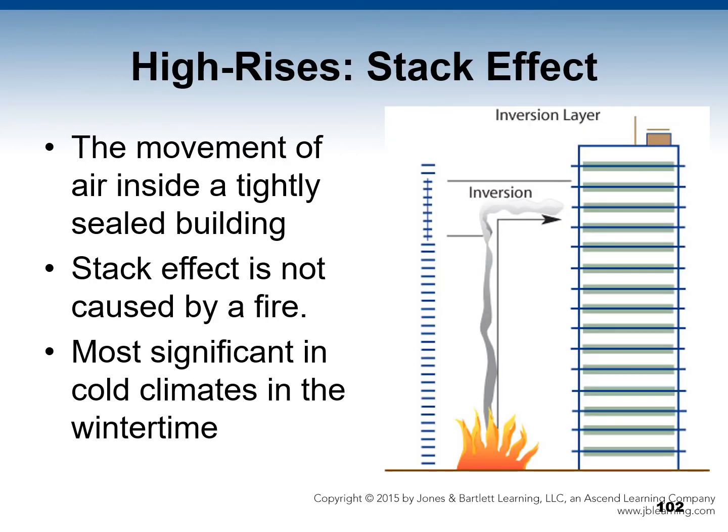With stack effect, this is the movement of air, and again, we're still talking about high-rises. Stack effect is the movement of air inside a tightly sealed building due to the difference in temperature between the air inside the building and outside the building. It is most significant in cold climates in the wintertime because of the great difference between the inside and outside temperatures. It is not caused by a fire, and the products of combustion ride these stack effect currents.